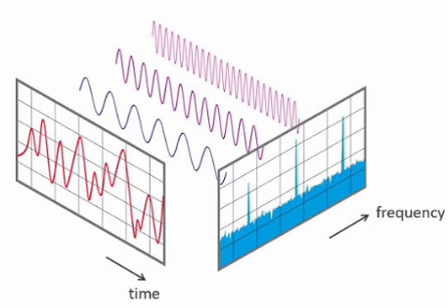Characterization of LTI systems using Z transforms. Causality: a discrete-time LTI system is causal if and only if the ROC of its system function is the exterior of a circle, including infinity. A discrete-time LTI system with rational system function H(z) is causal if and only if the ROC is the exterior of a circle outside the outermost pole, and the degree of the numerator is less than or equal to the degree of the denominator.